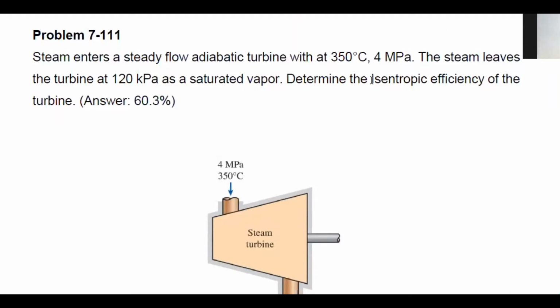Okay, so this is the new thing here. What are we talking about? Well, just like before, we had isovolumetric, which is the same volume, isobaric, which is the same pressure, and isentropic is the one that has the same entropy, right? Our entropy does not change. Okay, what does that mean? It means that we don't lose useful work or useful energy due to inefficiencies or irreversibilities of our process.